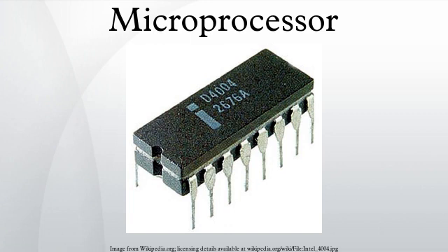The 9900 was used in the TI 990/4 mini-computer, the TI-99/4 home computer, and the TM990 line of OEM microcomputer boards. The chip was packaged in a large ceramic 64-pin DIP package, while most 8-bit microprocessors such as the Intel 8080 used the more common, smaller, and less expensive plastic 40-pin DIP.